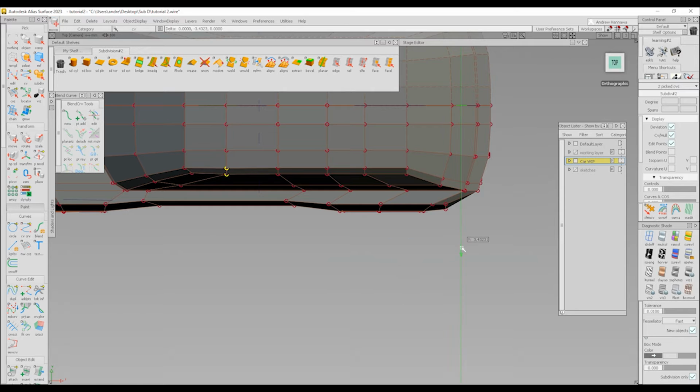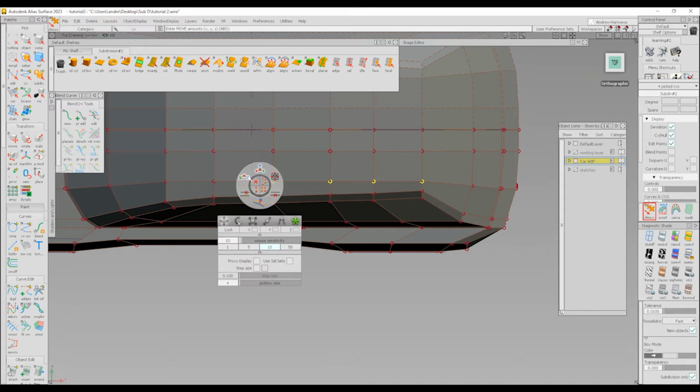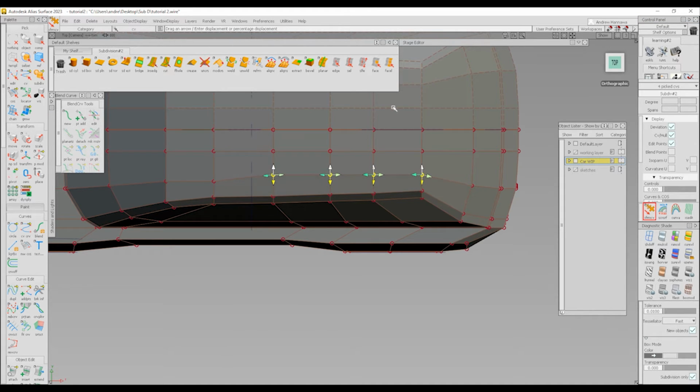Obviously, plan view also has shape, so we're going to create some plan view shape here. In most cars, it tends to go narrow towards the rear, so we're just going to create that effect now. And we're just going to do that by moving these CVs, like so. And we can also move these ones as well. And we can use the X-form tool to slide them.